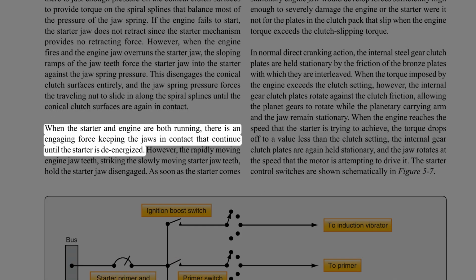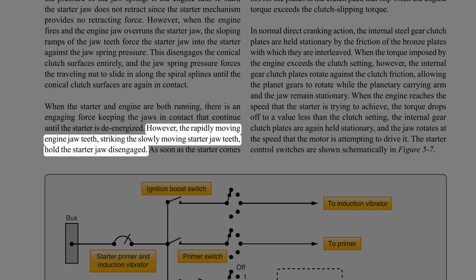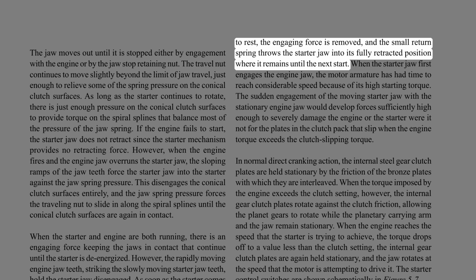When the starter and engine are both running, there is an engaging force keeping the jaws in contact that continues until the starter is de-energized. However, the rapidly moving engine jaw teeth, striking the slowly moving starter jaw teeth, hold the starter jaw disengaged. As soon as the starter comes to rest, the engaging force is removed, and the small return spring throws the starter jaw into its fully retracted position, where it remains until the next start.